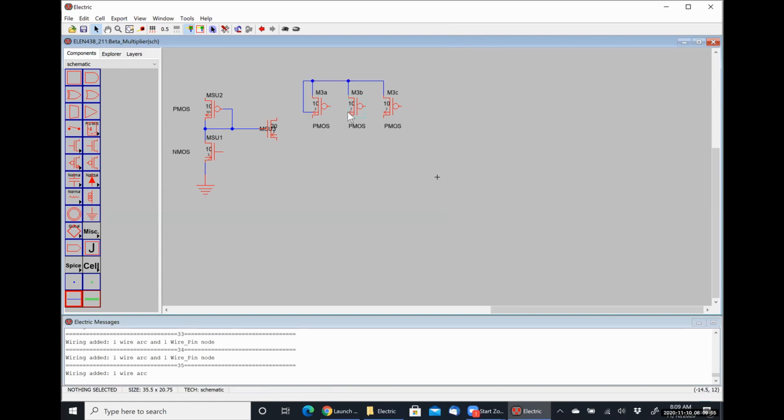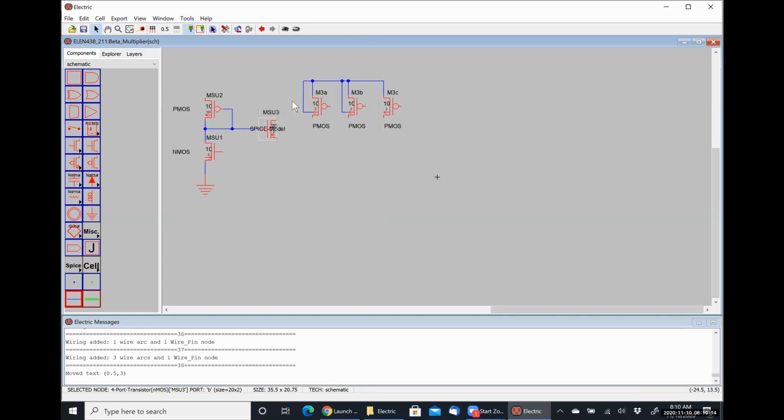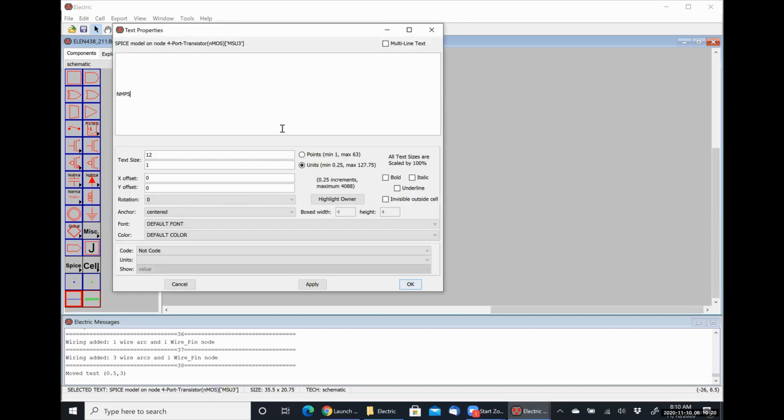Dr. Hartman. Yes, sir. For MSU3, I don't think you ever set the spice model. You are absolutely correct. Thank you for that. So let me select the right thing. There we go. So the SPICE model needs to be set to NMOS. Thank you very much. Or I would have forgotten it, and then when we tried to simulate it, been like, why isn't it working?